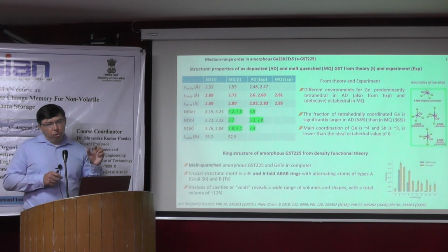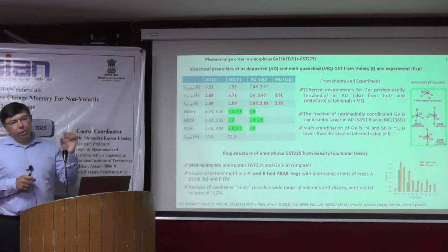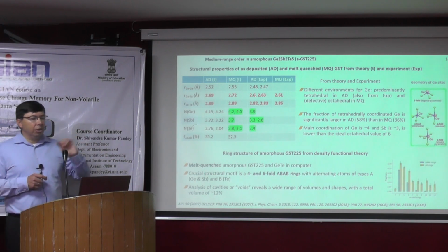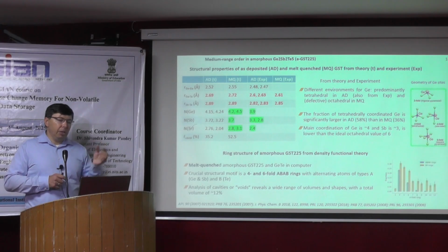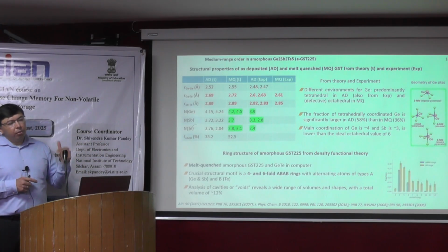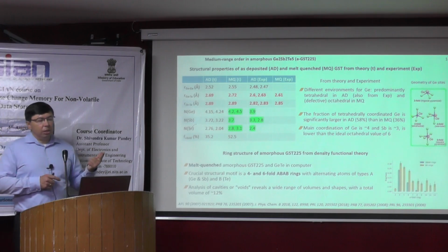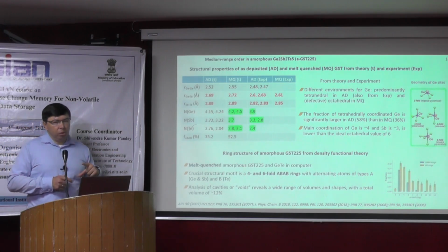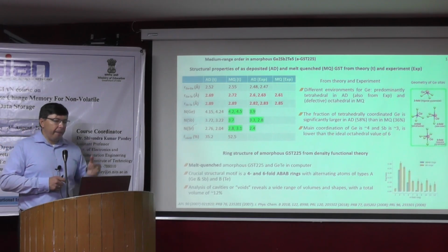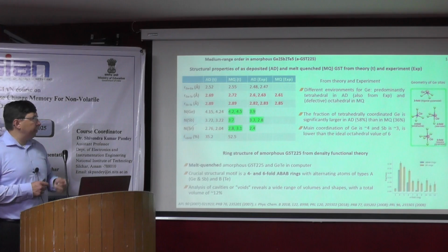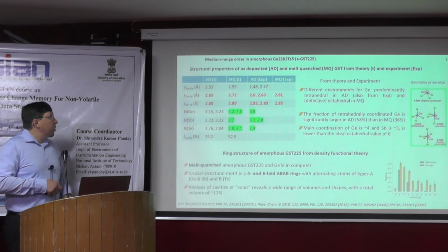Also, if you operate your devices optically or electrically, you first make several switching cycles. You make the deposition and then let the device switch several times, and in the end you switch between the melt-quenched and crystalline states, not between as-deposited and crystalline. So you have this melt-quenched to crystalline phase transition.